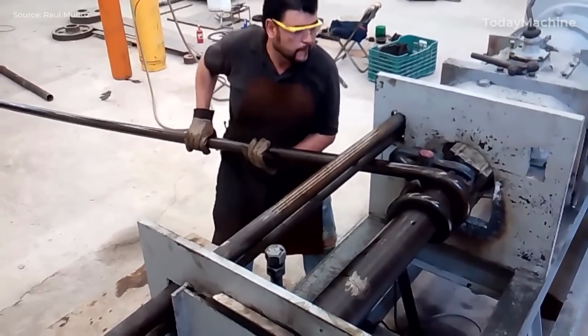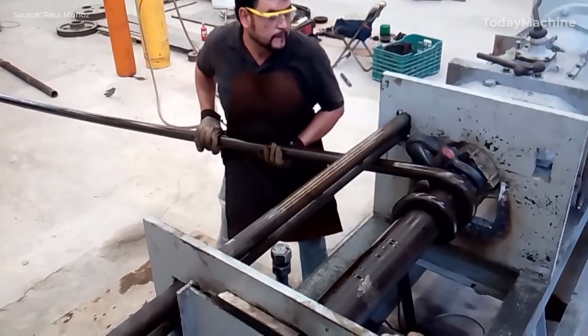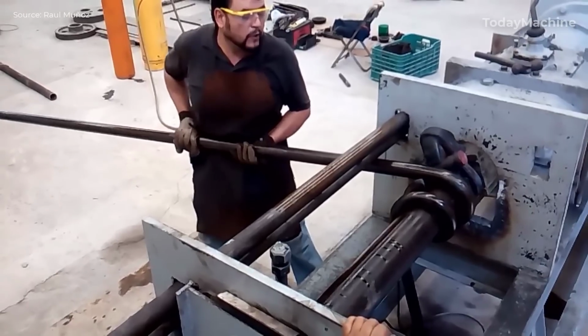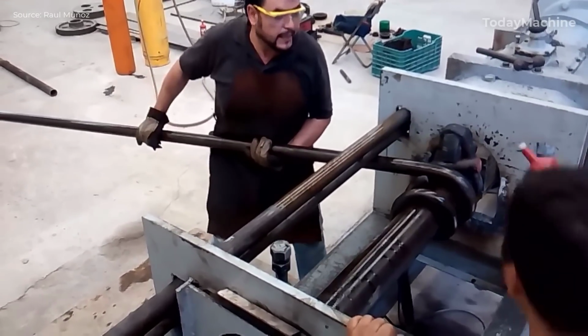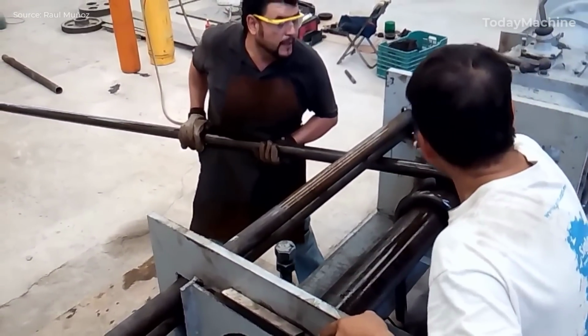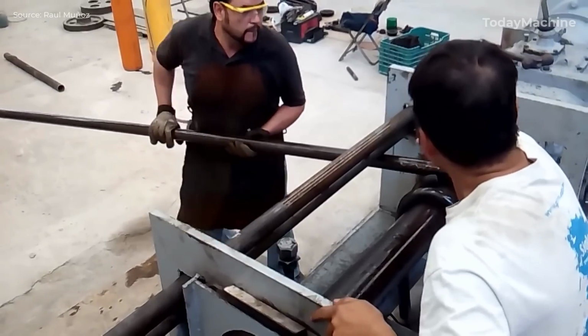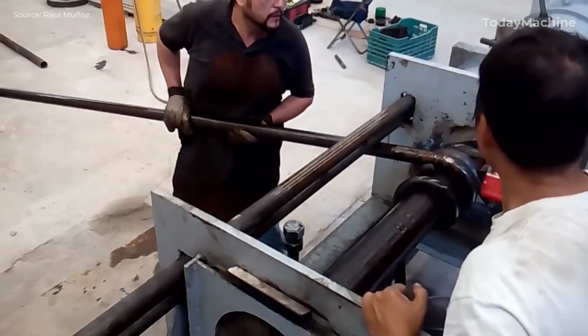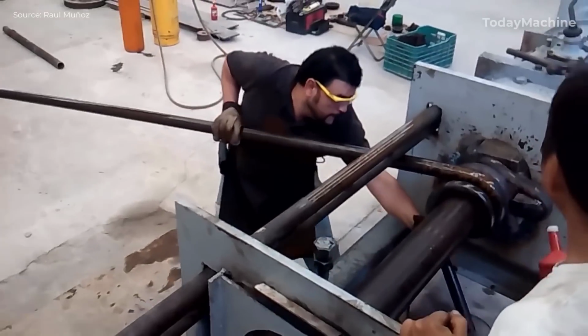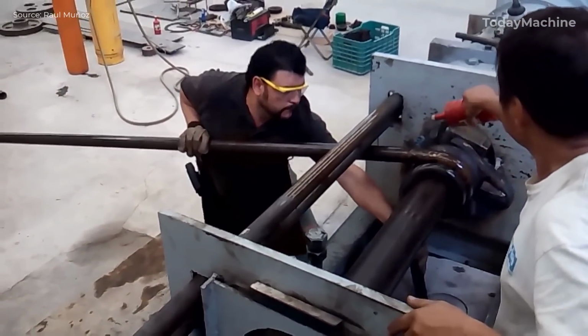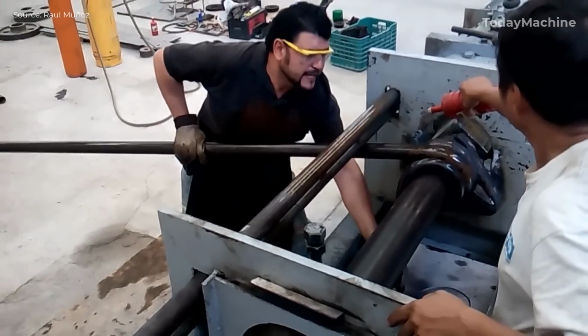The selected steel is often supplied in coil form, with a tensile strength between 250,000 psi to 300,000 psi. The material's hardness before the winding process typically falls between 45 to 50 HRC, Rockwell hardness, ensuring it can withstand the stress induced during the winding process.